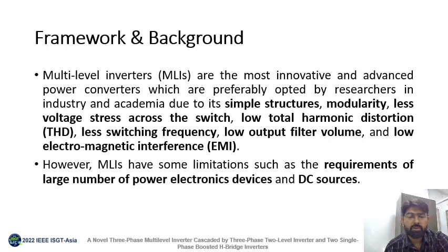Framework and background. Multi-level inverters are among the most innovative and advanced power electronics converters, preferably opted for by researchers in industry and academia due to their simple structures, modularity, less voltage stress across the switch, low total harmonic distortion, less switching frequency, low output filter volume, and low electromagnetic interference. However, MLIs have some limitations, such as the requirement of a large number of power electronic devices, a large number of gate driver circuits, and DC sources, etc.